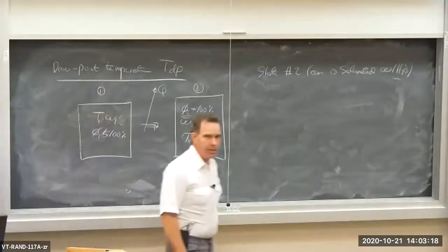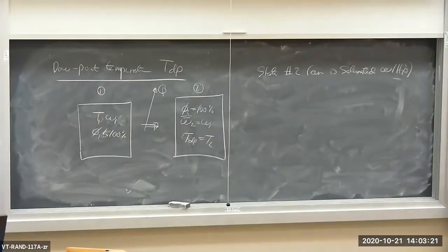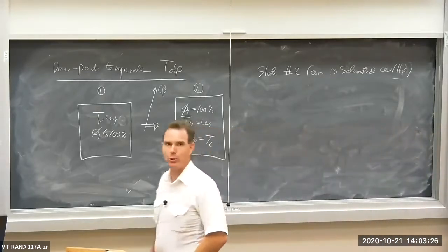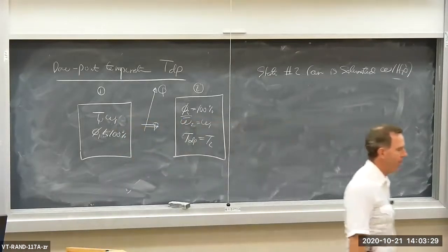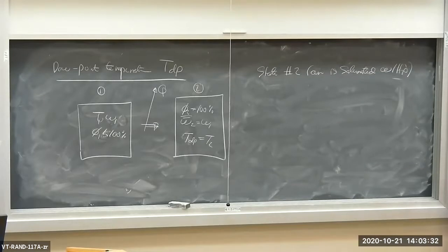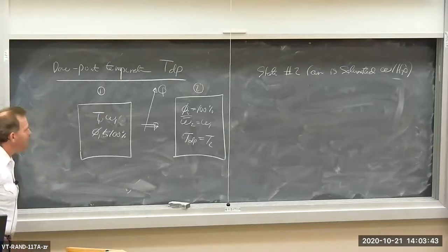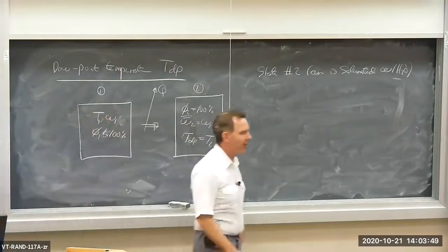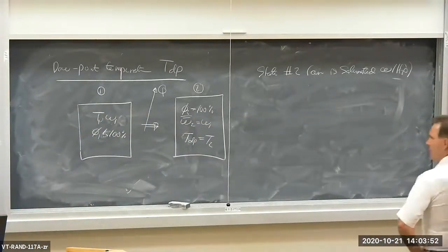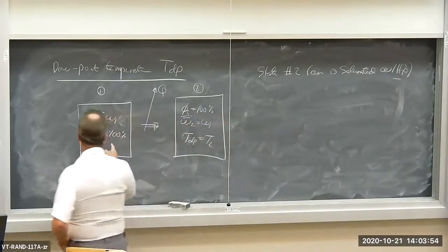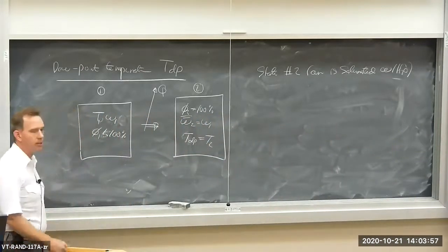Okay, let's make this idea of the dew point temperature a little bit more rigorous. The temperature at which the moist air is saturated with H2O. It can't take any more H2O. It can't absorb any more H2O vapor into the mixture, so it's saturated. Its relative humidity is 100%. So let's say we start off with a room or a container of moist air at state 1. So we have a temperature T1, an absolute humidity or humidity ratio omega 1, and then we have a relative humidity that is less than 100%. So we are not saturated at state 1.